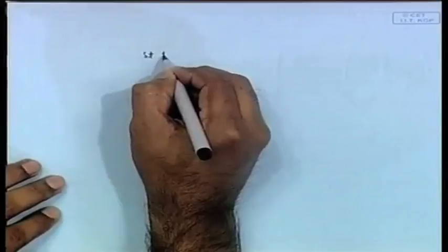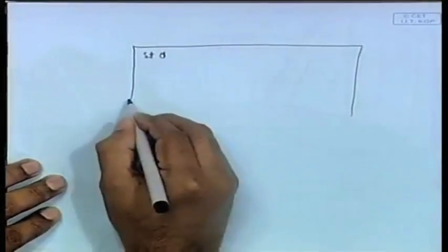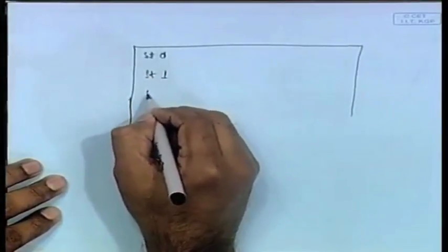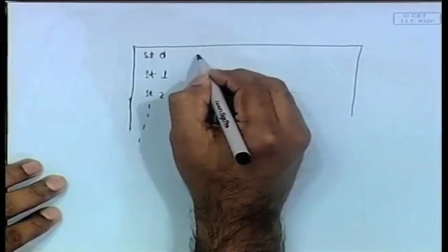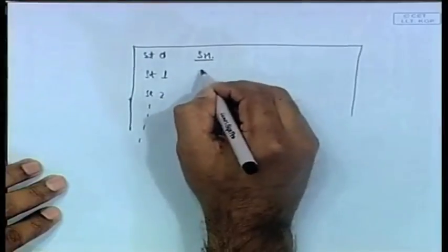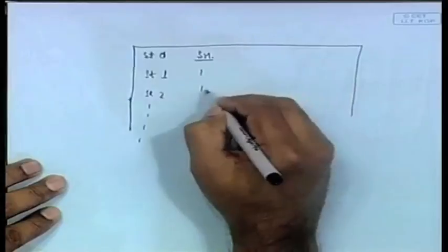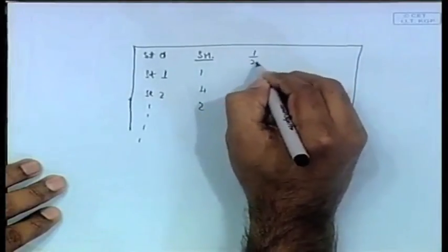We will do that, but you will write a table like this: station 0, station 1, and so on, stations like this you will write. Then you will write the Simpson's multiplier, 1 4 2 4 or like that. Then here you are writing the half ordinate cubed.